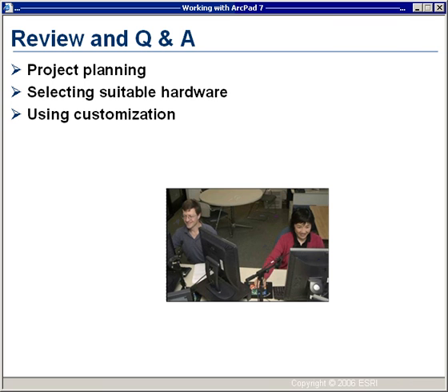William from North Charleston asks, does snapping work when using a GPS? And the answer is yes. If you have snapping enabled, the GPS coordinates that you're receiving from the GPS will then be snapped to existing features. Obviously, if you are using a GPS and you have snapping enabled, you need to determine whether you want the absolute coordinates from the GPS or whether the existing coordinates of existing features override these GPS coordinates.